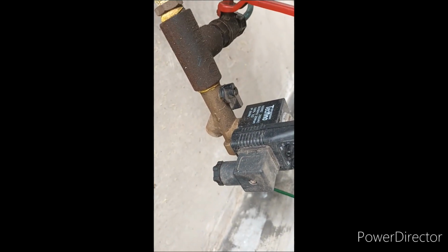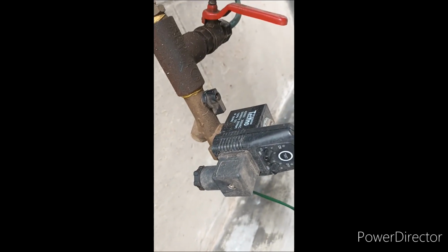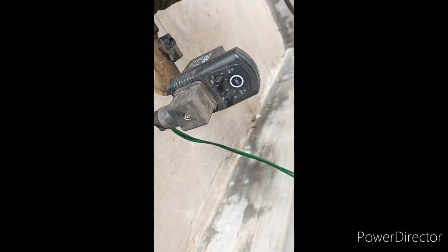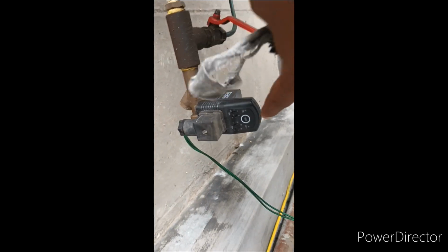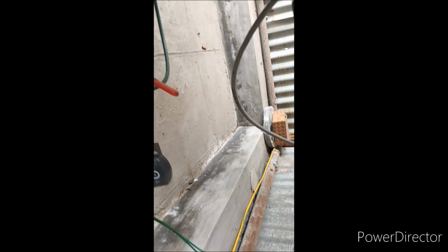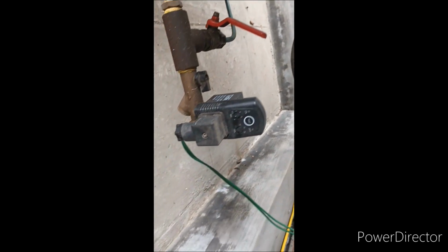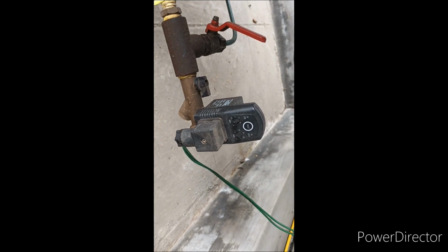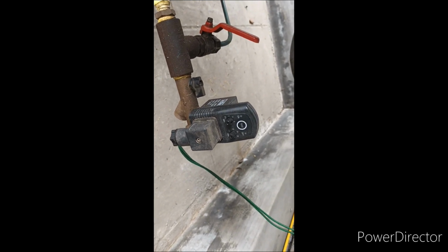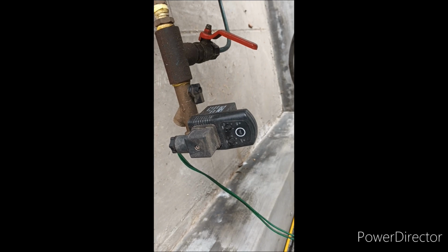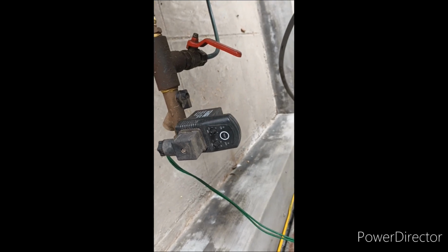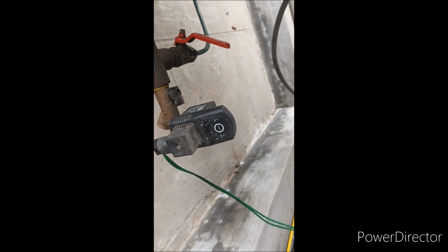If there are any lapses in the drainage of moisture, it can cause excess load on the air dryer, resulting in damage to the attachment. It has a test button. Whenever we need to check whether this is working or not, we need to test it from the test button. It is important to drain the concentrated moisture at the correct interval, so we can avoid manual errors. This is the function of the auto drain valve.